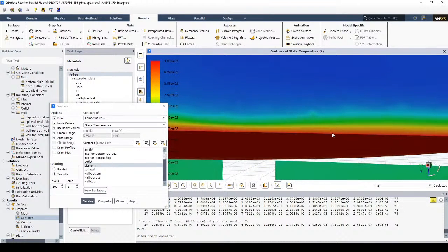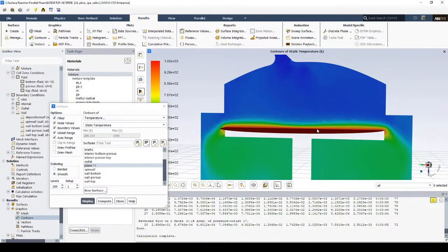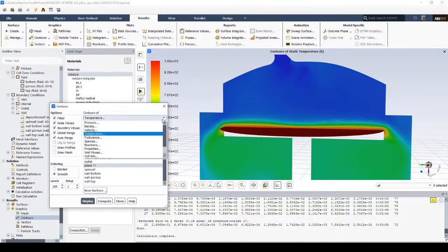And this is a case where having an inflation layer near the deposition region is really important, because we want to have the right temperature gradient. Again, you can put a heat source on the bottom too, and you can see how well you can control the temperature. It does end up being quite useful.